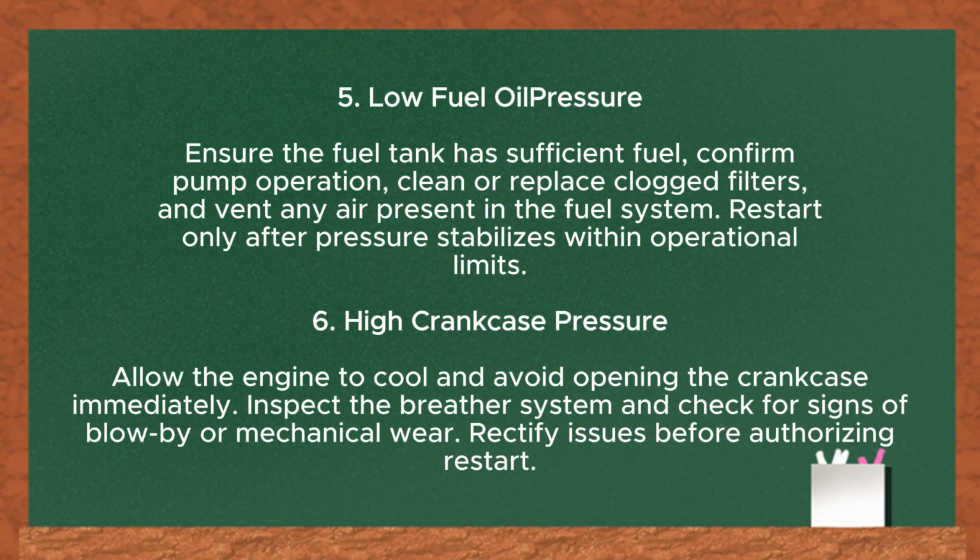And the 6th, high crankcase pressure. Allow the engine to cool and avoid opening the crankcase immediately. Inspect the breather system and check for signs of blow-by or mechanical wear. Rectify issues before authorizing restart.